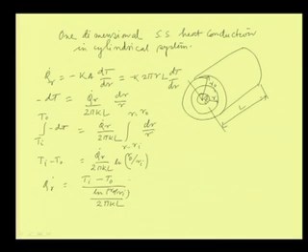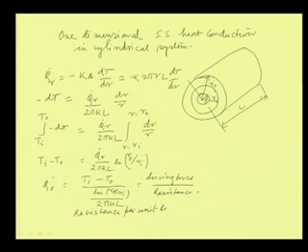So, as we have seen in the case of the plane wall, here also you can see that the numerator is the driving force for heat transfer and the denominator is the resistance. The resistance per unit length will be equal to ln R O by R I divided by twice pi k, when L is equal to 1, per unit length of the cylinder.